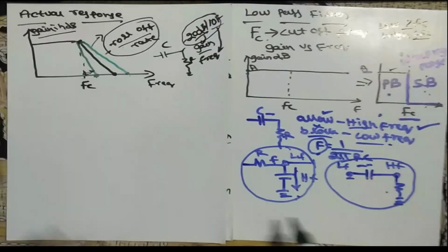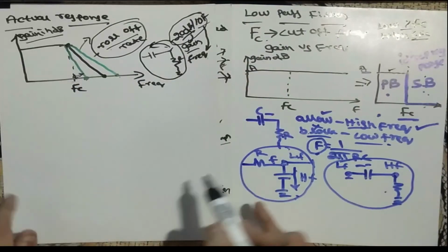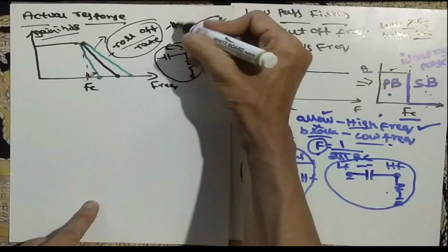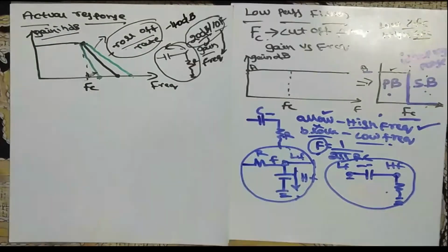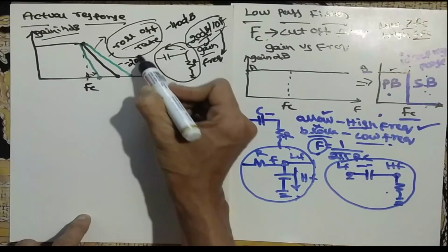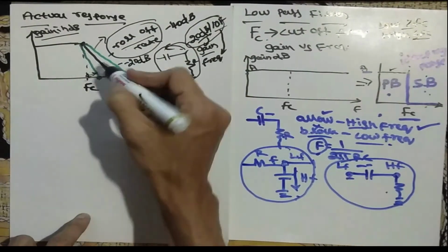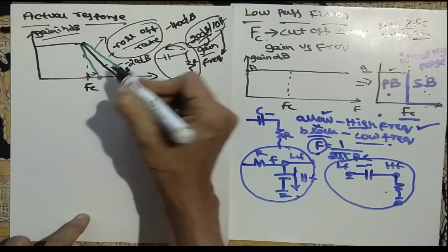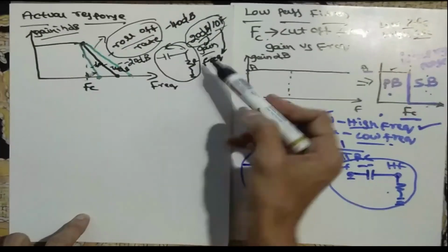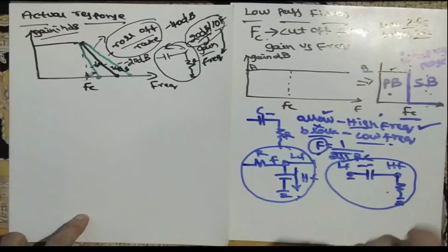Similarly, we can take this same circuit and connect it in series once again. Then, instead of minus 20 dB, it becomes minus 40 dB. The last one we called minus 20 dB something, because it will take a lot of time to reach here. Then minus 40 dB is this, and this is called minus 60 dB. So when you are talking about more capacitors and resistors, this is called the order of the filter.